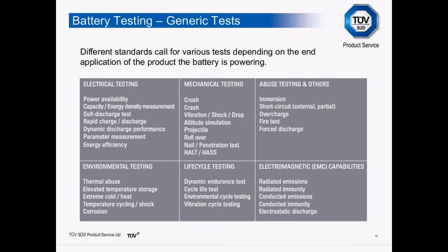There are also more performance-related tests, such as life cycle testing, as I mentioned before. So check how well the battery pack lasts under continuous use. Sometimes, especially in the automotive industry, they have test profiles of typical charging and discharging under braking, acceleration, and stopping. And this gives a good feel to the design engineer that this battery pack product would be suitable in a real world environment.